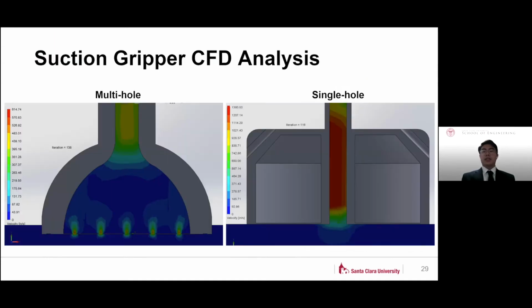A variety of simulations were run throughout the year to quantitatively observe theoretical velocities and pressures and qualitatively better understand flow. SolidWorks Flow Simulation was the tool used to accomplish these basic goals. Some assumptions used included the environmental pressure at 14.7 psi, the vacuum volumetric flow rate, which based on the spec sheet is 12.2 inches cubed per second, the tubing, which was modeled at 6 feet with one 90-degree mitered bend based on the real prototype, and a simulated leaf placed 1.3 inches from the gripper.